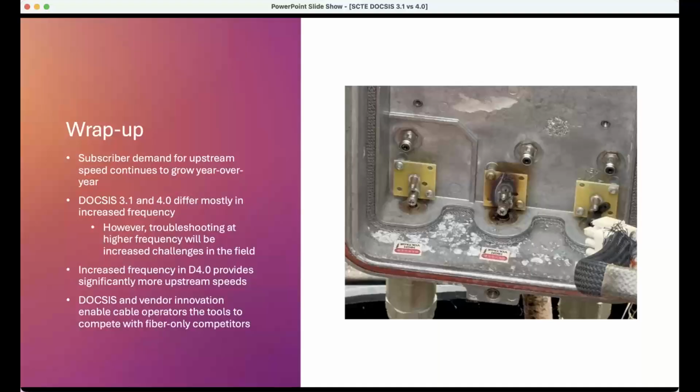So the pipe, at 4096, we have a lot of capacity. That's a very fat pipe going into that cable modem. When the impairment arises, the modem may drop down to 1024 QAM. If the impairment's too great, it may drop all the way down to 256 QAM. So now the amount of data capacity that can flow into that modem just gets smaller. 256 QAM is lower bits per second per hertz than 4096 QAM. So that negotiation will drop down while that impairment is present.